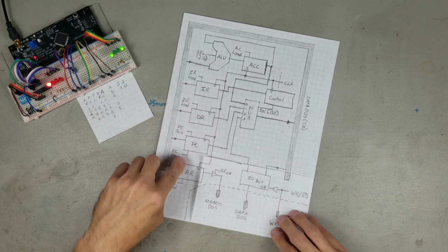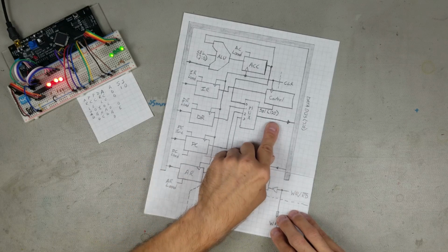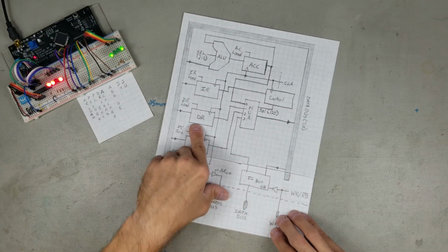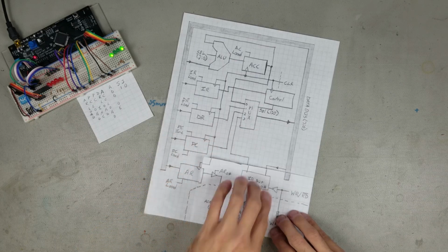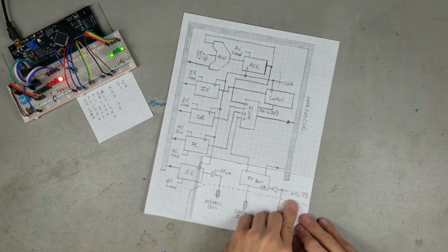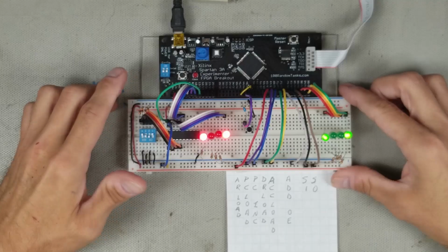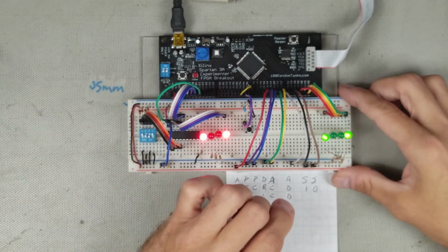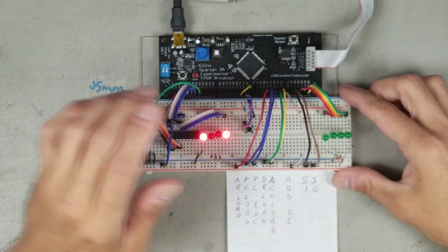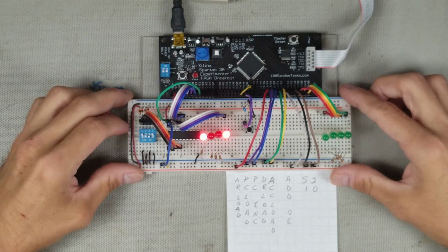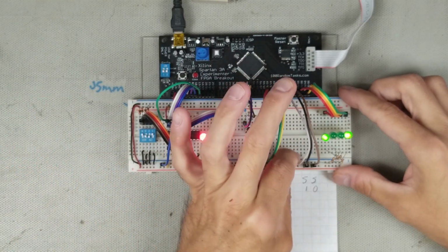Suppose we want to send what's on the data register to the external data bus. First, by setting the select lines to 01, it funnels the data register through the multiplexer and onto the internal data bus. Then by setting the read-write line high, the internal data bus is sent out to the external data bus. If I set the AR output enable line high, the LEDs turn off, as this puts the address bus into high impedance. This will allow other devices to access the memory bus if needed. We know that works, so I'll leave it set low for now.